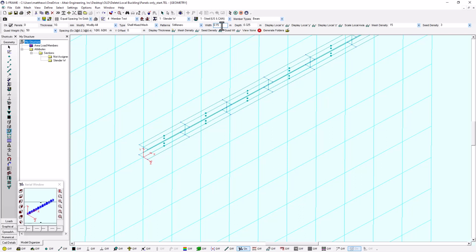These are going to be stiffeners, so this is basically going to occupy the space between our flanges and our web. So 0.15 meters is my width, and 0.325 meters is my depth, and that would be found using the dimensions tool in the CAD details window. I can also specify my mesh parameters, and at the bottom here I have this spacing command that allows me to specify spacing for this particular application. And this will all be with respect to the coordinate system.